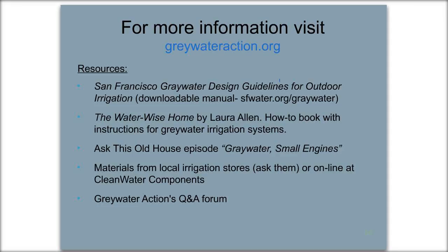I have a slab foundation. Does that mean that I can't do a graywater system for my shower, sink, and kitchen graywater? If you have a slab foundation, your washing machine will be your best bet to start with, because you access the water by the machine from the discharge hose. First floor showers are probably not going to be an option. You can get creative, but without doing some kind of plumbing overhaul, you can't really feasibly access the shower on the first floor of a slab foundation. Maybe you have a second floor bathroom, and then you possibly could access that water.